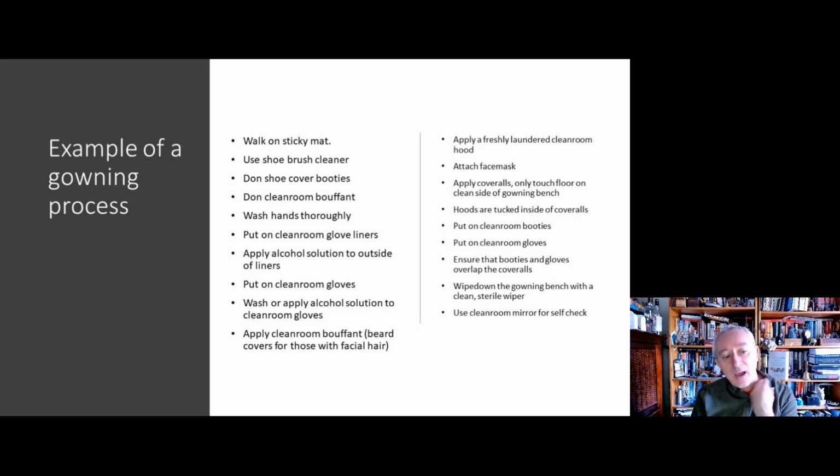It's also important that when we're going into the changing rooms that we're walking across a sticky mat or Dyson flooring, which is also a form of a sticky mat. It just doesn't feel as sticky, but it's polymeric flooring that is designed to electrostatically attract particles from your feet, and that we're going through changing in the correct order, and we're having lots of controls. We don't have things like hoods poking out of our suits. We're doing good practices like always wiping down the step over bench before we cross over it.